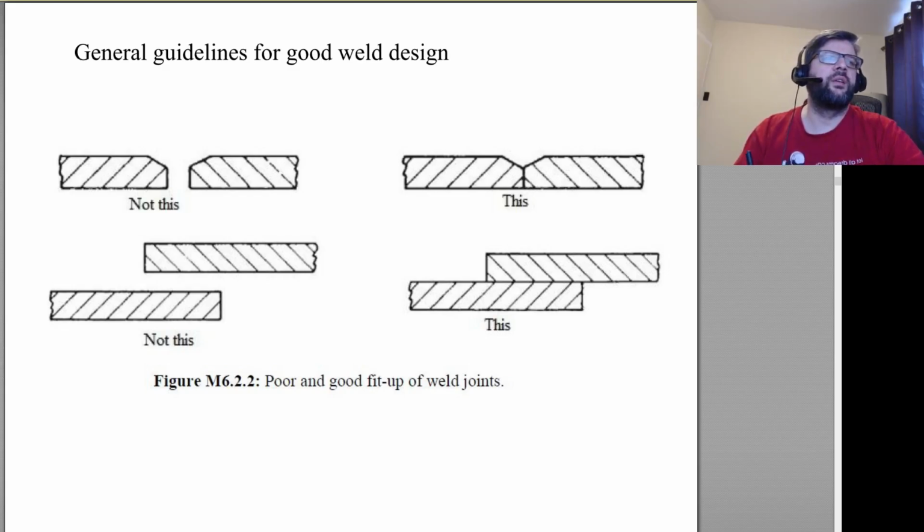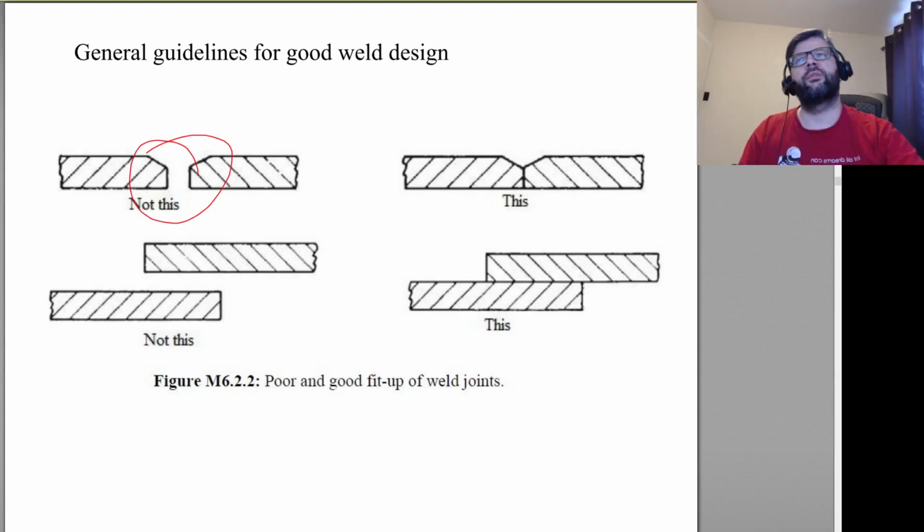Typically speaking, you want to eliminate gaps before you start welding. So if you try to do something like this, again, you will get a full through thickness weld, but it'll be a pain to try to build it up. Whereas if you do a weld like this, then typically, once you're done, the weld might look something like this. So you're probably going to end up with this little gap at the end here, but again, it'll be far quicker and easier to do a weld like that.